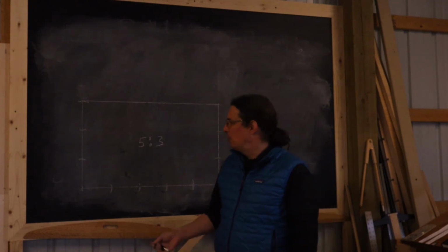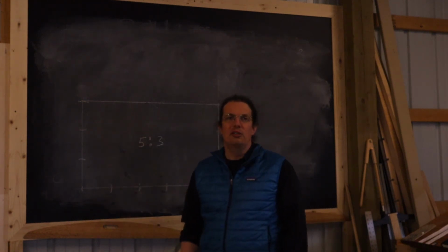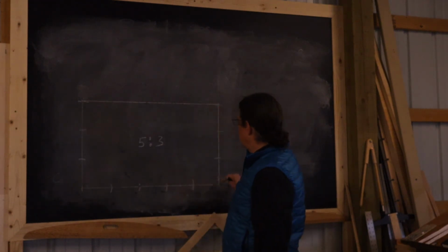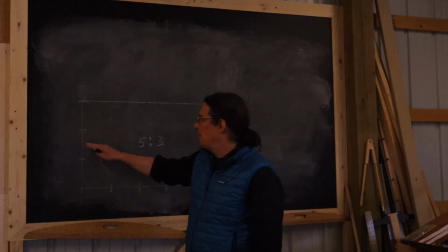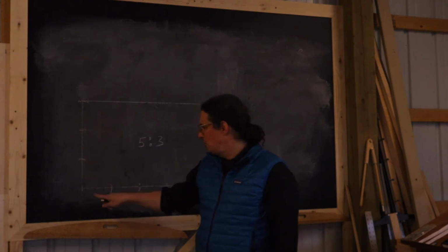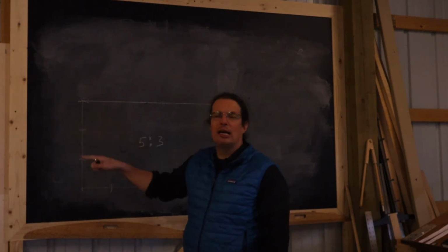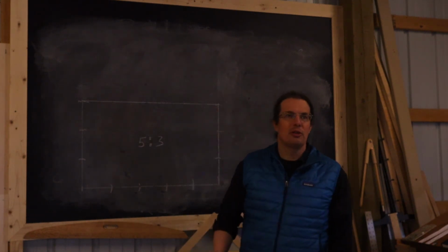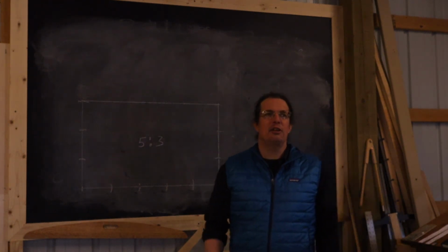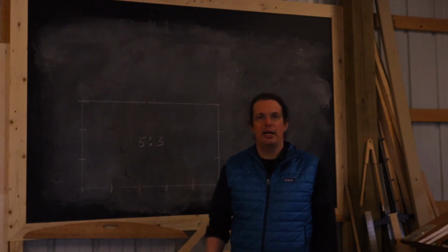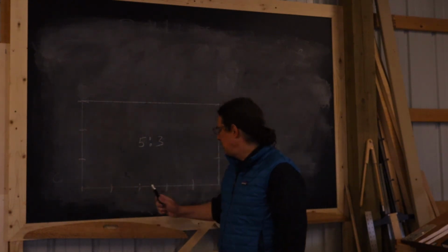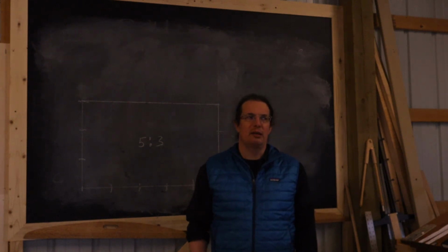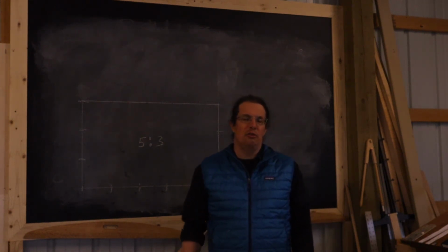And once you've done it, the rest of this construction proceeds as before. You mark off your steps, you draw your vertical lines with a framing square, you step off that same distance, this step size, however many times you've chosen vertically, and then connect the tops. So it's not much different, it's just that you've got to take a little bit more care on dividing up between the endpoints of your segment into a chosen number of pieces.